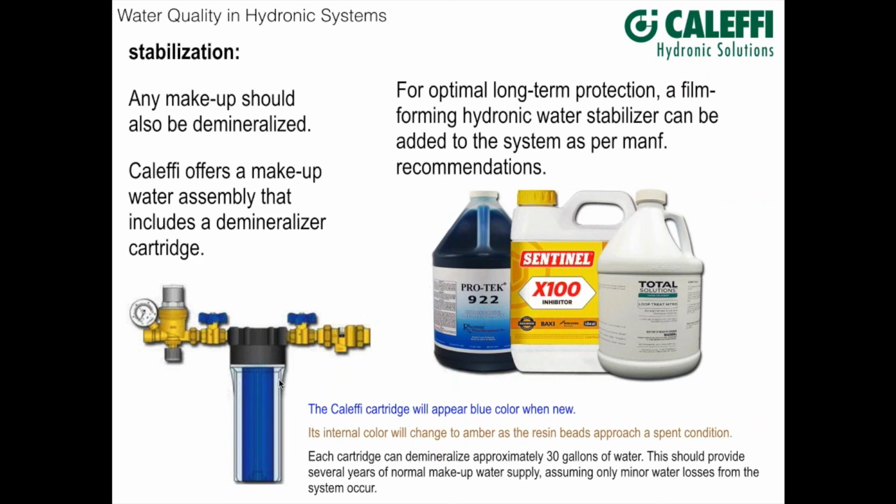And this has been set up so that when the cartridge is new, you have this characteristic blue color to it. And again, any makeup water that flows through here, same thing with the resin beads happens. The ions are stripped out and pure water is put back in, but as with the larger unit, there's a limit to how many ions can be bonded to these resin beads.